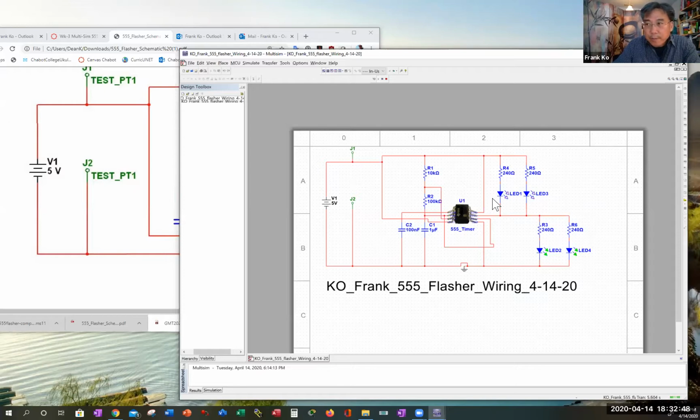Edwin, you have a question? Yeah, so I'm doing exactly what you did there. I tested it out. What's the purpose of J1 and J2 when it comes to Multisim? Not with Multisim, but actually they turn out to be positions on the circuit board that we can connect for junction for outboard power. On the Multisim, it's a 5 volt. On your board, it will be to a power pack, battery pack.